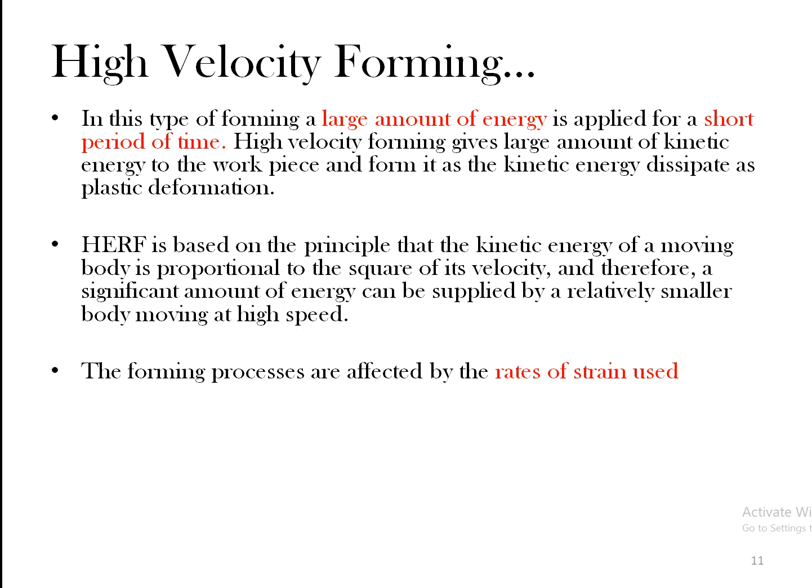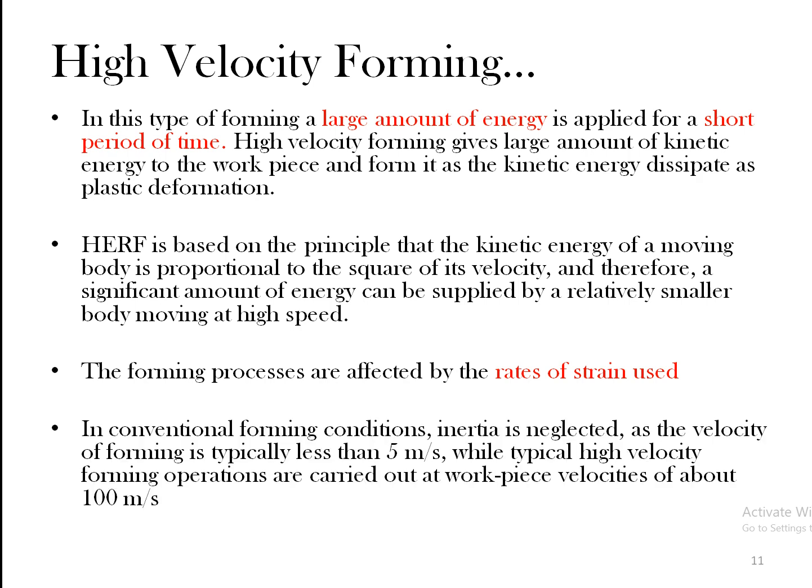The forming processes are affected by the rates of strain. We'll see in lecture video 3 how the strain rate affects the forming process. Okay. So in conventional forming, the inertia is neglected as the velocity is very low, that is, less than 5 meters per second. Okay.